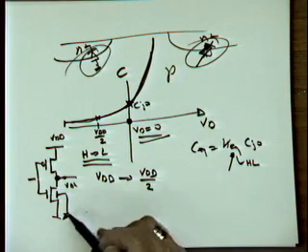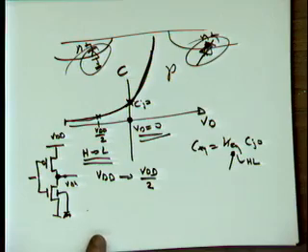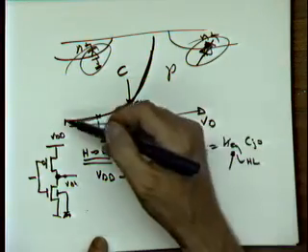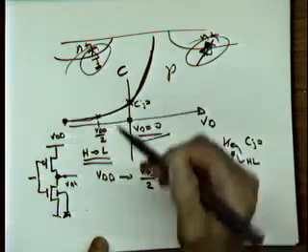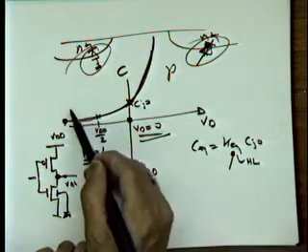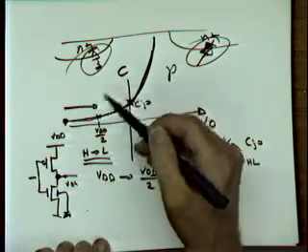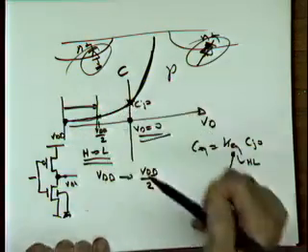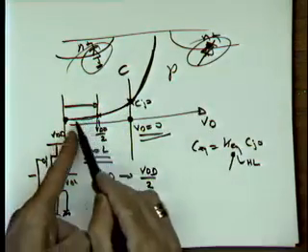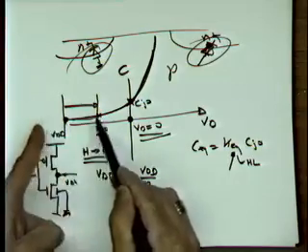The substrate is at 0, so what's the voltage over the diode? It's VDD, reverse bias. So we're in this point. And then we're going to start discharging the capacitance, going to this point in the middle here. And again, we can find a K equivalent value for this particular interval.